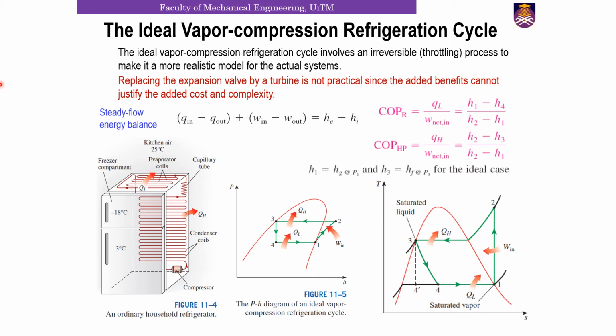So it is only natural to look at it first as a prospective ideal cycle for refrigerators and heat pumps. The two isothermal heat transfer processes are not difficult to achieve in practice, since maintaining a constant pressure automatically fixes the temperature of two-phase mixture at the saturation point. So this is not a problem.